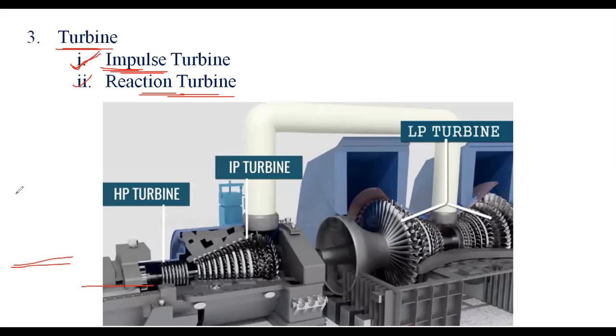Generally in the thermal power plant, the efficiency we are getting is only 29%, with 71% in terms of losses. By using the flue gases for reheating in the intermediate stages, we are improving the efficiency by 5 to 10%, so we are getting 30 to 35%.